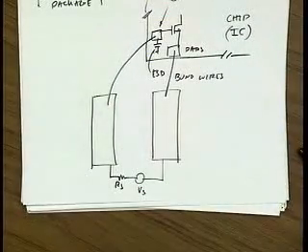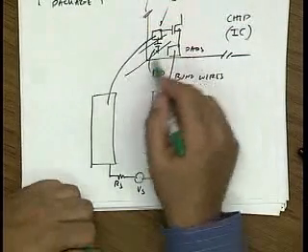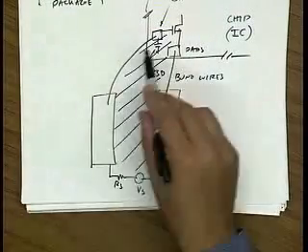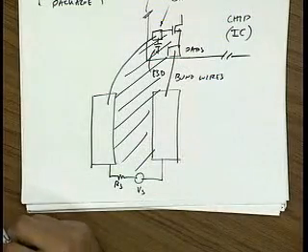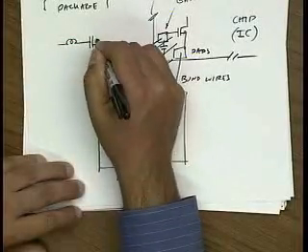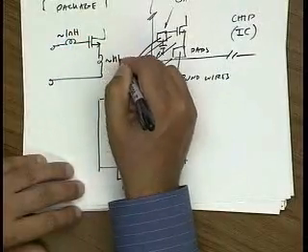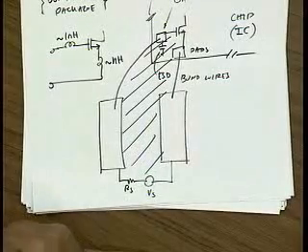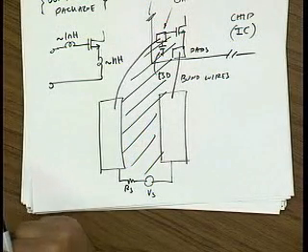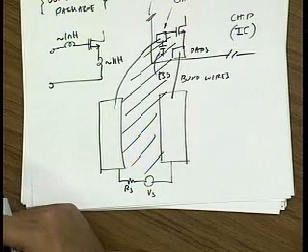And if you see this loop, it's a physically large loop. And if you run a simple calculation, you can see that the magnetic flux in this loop generates an EMF which is substantial. And in circuits, we model that by just putting inductors in series with these terminals. Okay? And these inductors are on the order of nanohenries. Now, there's lots of packaging technology to try to reduce these inductors. But at the end of the day, you're going to end up with, at best, hundreds of picohenries up to tens of nanohenries if you're in a really large package. Okay?